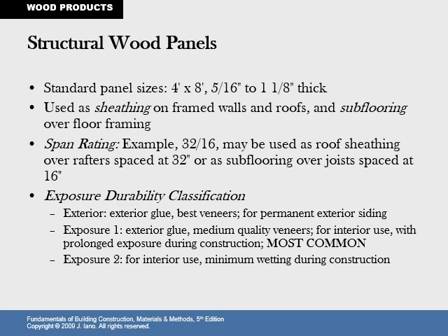Exposure 1, exterior glue, medium quality veneers for interior use with prolonged exposure during construction is most common. And Exposure 2 for interior use, minimum wetting during construction.